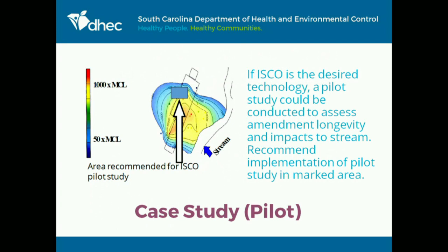So where would you recommend it? Right in the core? I mean, that is certainly one option. If you do put it in the core, then there's a risk, if groundwater flow is towards the surface water body, that you will have contamination coming into it. And that's going to make it difficult to interpret the pilot study, because if your concentrations go up because of migration of contamination, that could counterbalance the effect of the pilot study.